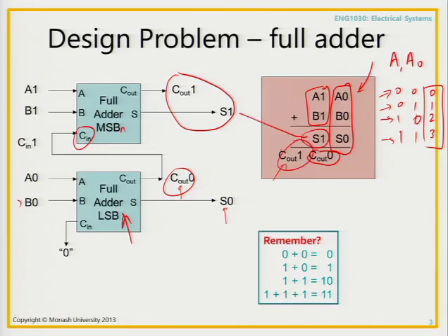And this is a basic computer. If I want to add two numbers, I convert them into binary, and I put the corresponding voltages, 0 or 5 volts, depending if I want a 0 or 1 for the binary, into all these inputs. And hey presto, the answer comes out on S1 and S0, what the sum of those two numbers is. That's the most basic computer.